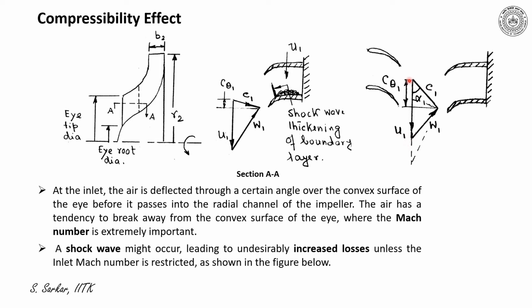This is the velocity triangle with a positive swirl at inlet, and the dotted triangle I have superimposed here is the triangle without guide vane. Now you can appreciate that W1 has decreased. Thus, the relative inlet velocity can be controlled by providing a guide vane at inlet.